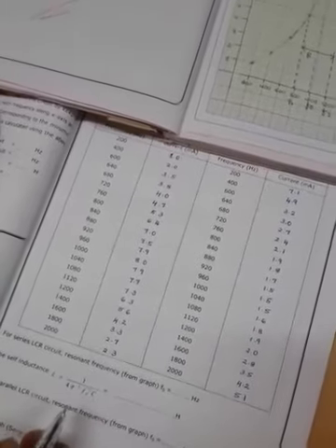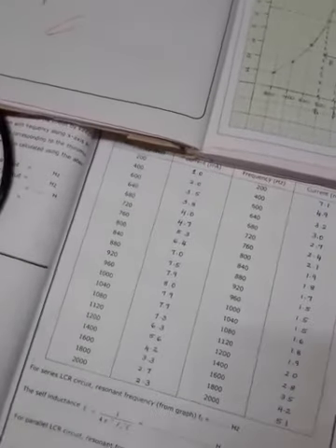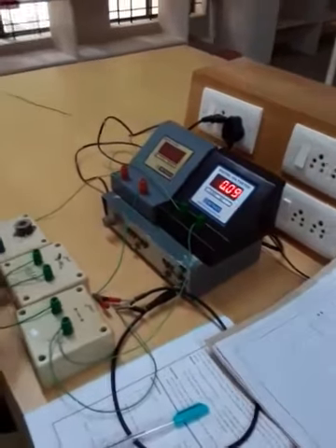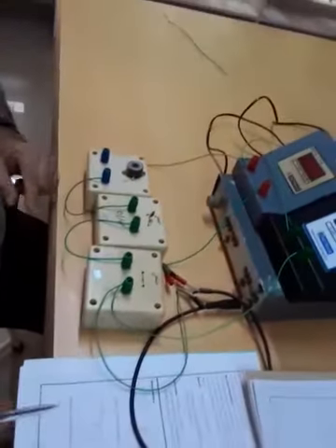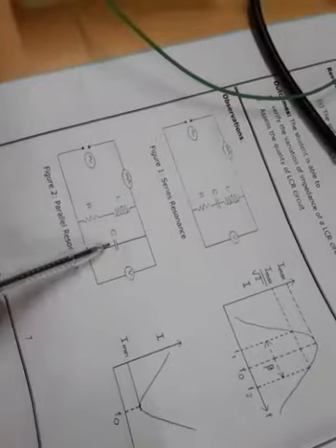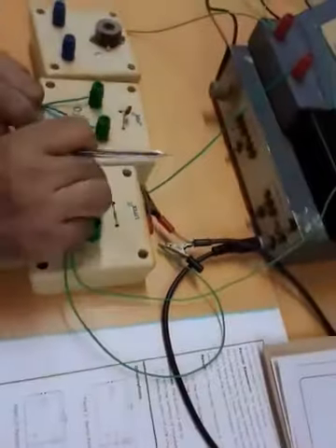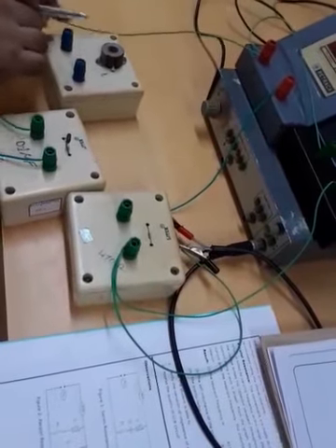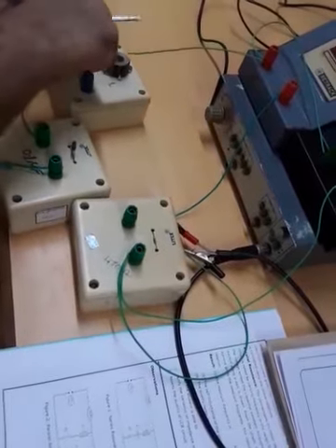Now the same experiment can also be repeated for the parallel circuit. For the parallel circuit, you put off the circuit connections, you put off all the batteries, and here you connect the inductor and resistor in series, but the capacitor is in parallel. So what I do is I will remove this capacitor and connect the capacitor in parallel with the inductor and resistor circuit.